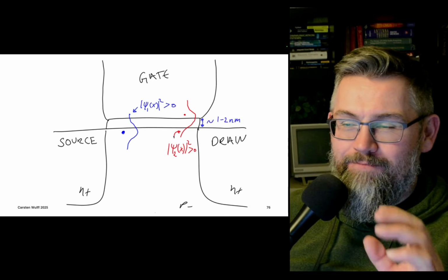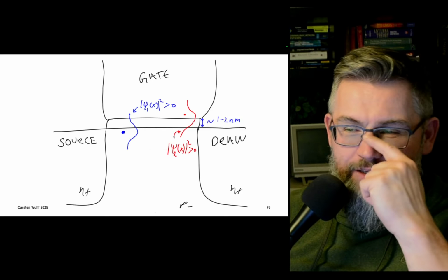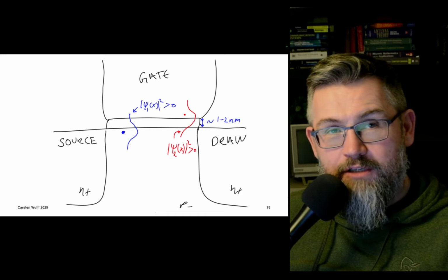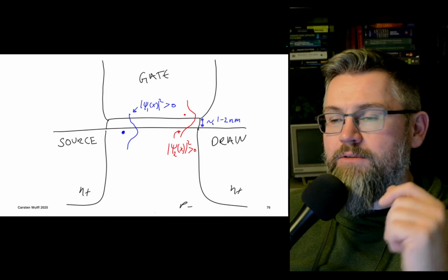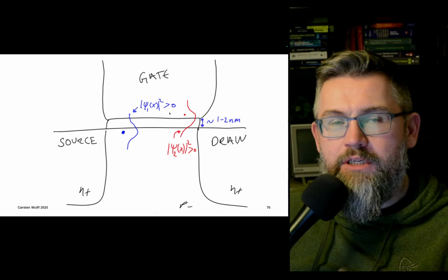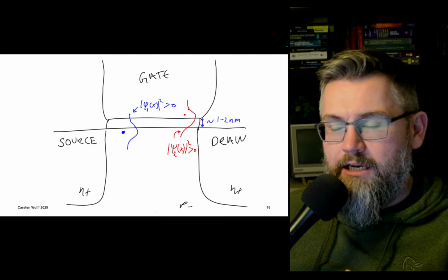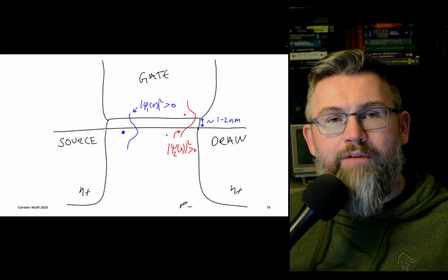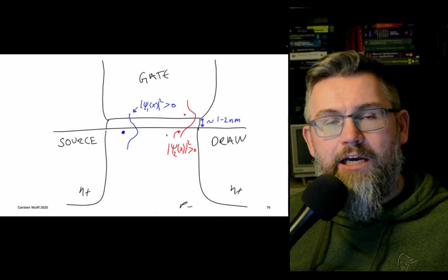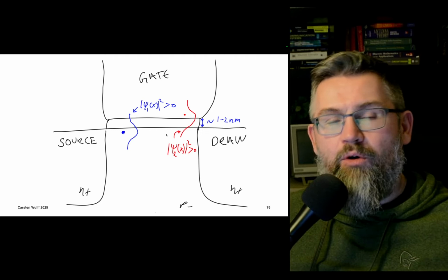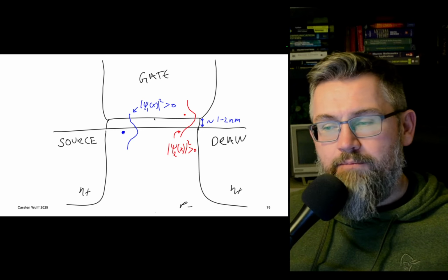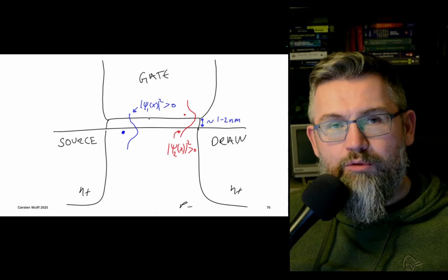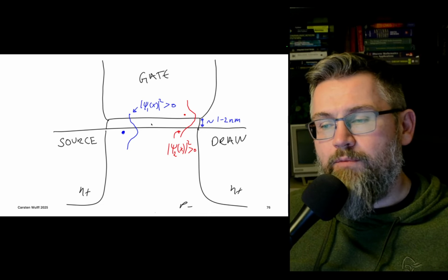Gate current is not that big a problem anymore. It used to be horrendous in 65 nanometer because we had silicon oxide thinned down to a few nanometers. The wave function of the free electron, in both the gate and the channel, actually extended beyond the gate oxide, which means the electrons could tunnel through. There will be a tunneling current through the gate.